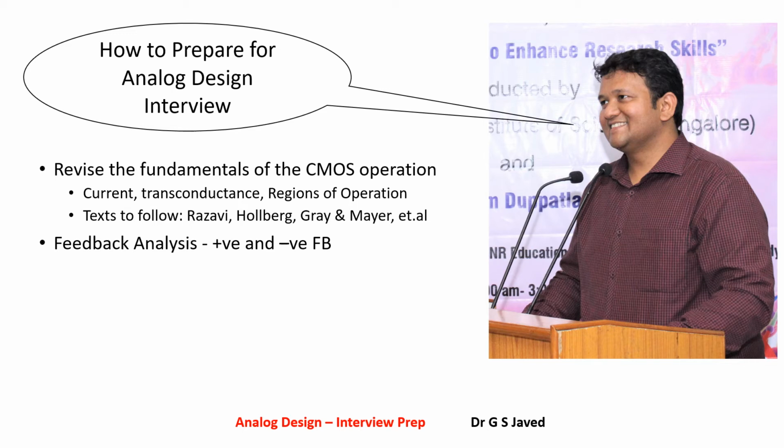In a negative feedback, you would see a corrective action or a control loop being used. A quick example of a control loop in a timing sense would be the phase lock loop. Another would be the delay lock loop, and in the power sense you would find that to be your bandgap reference circuits or your low dropout circuits or LDO devices.